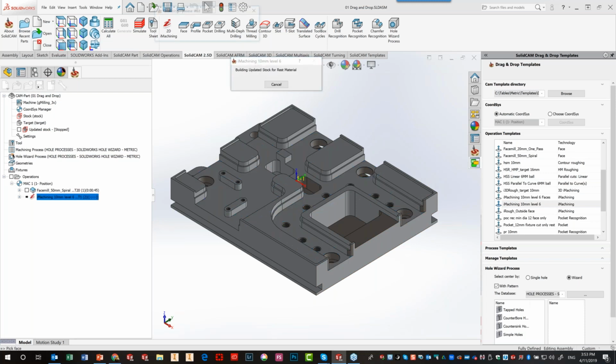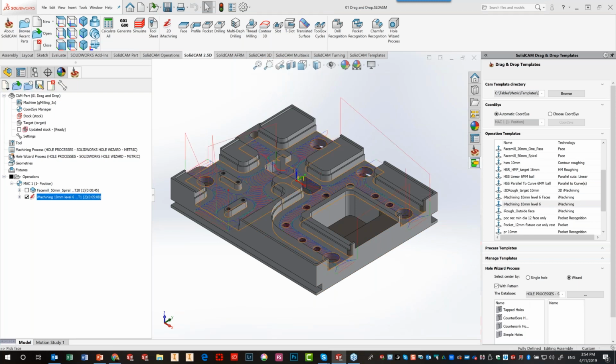And as you can see, it's being calculated, and you can see the tool path created on those areas over there on this entire face. If I want to do it to this face over here, and all of these faces, I want to have that in one operation, I can drag it to this face over here. Before I let go of my mouse, I just hold my control button and then just click on every single one of those surfaces.